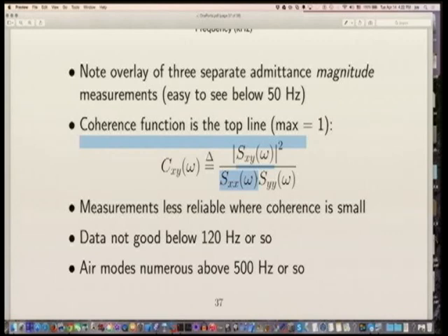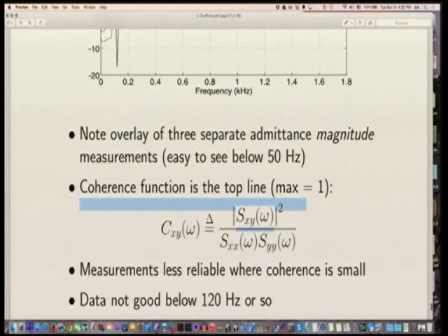Let's say we have a hole, a null somewhere in our excitation. Then that's a 0 in the denominator. Who knows what's going to happen? We should get a 0 in the numerator as well, but it's indeterminate. And if there's any noise whatsoever, you'll see it in the numerator, and you'll just get garbage, right? So there are sources of noise.